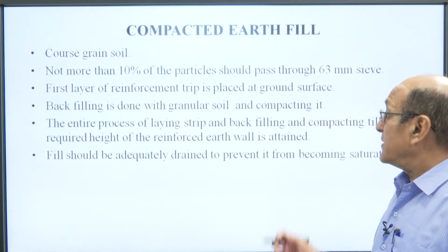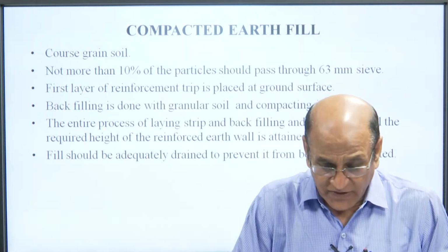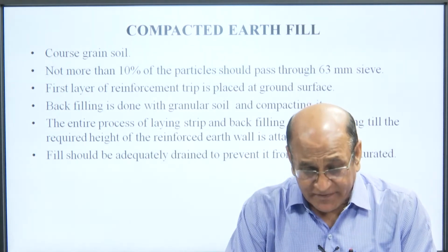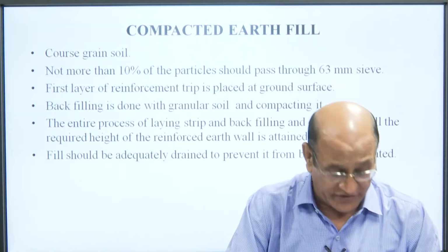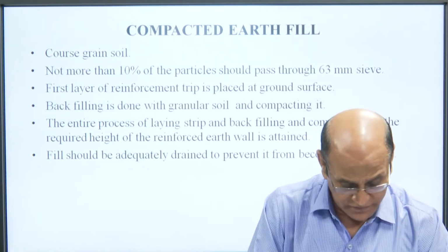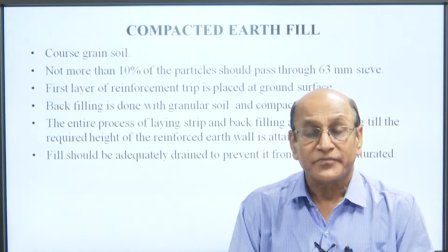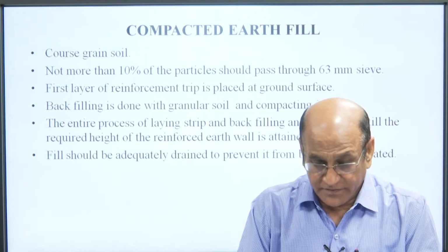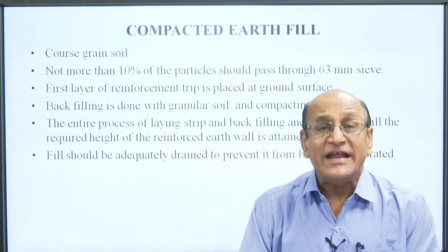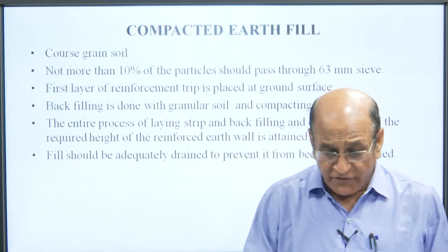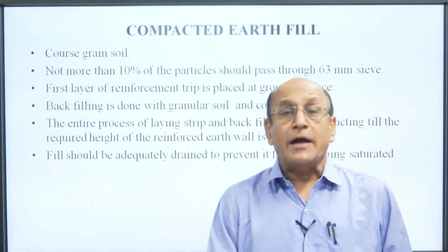The first layer of the reinforcing strip is placed at the ground surface. Backfilling is done with granular soil and compacting it.